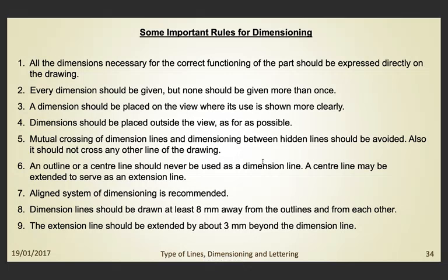These are some important rules for dimensioning. Just go through it. All the dimensions necessary for the correct functioning of the part should be expressed directly on the drawing. Every dimension should be given, but none should be given more than once. And continued.